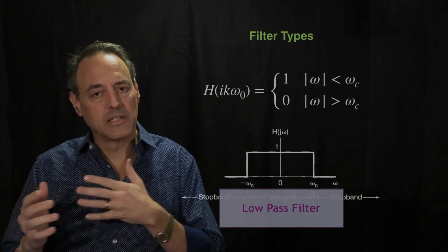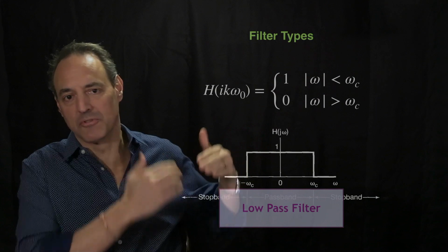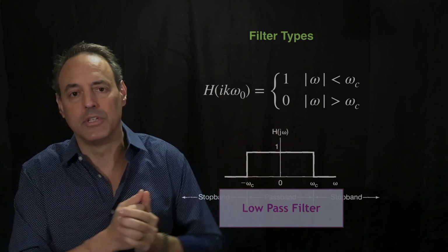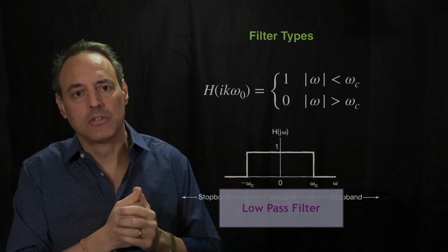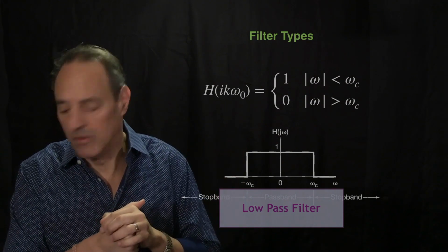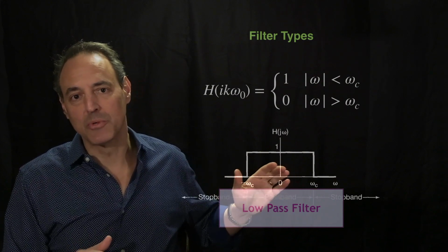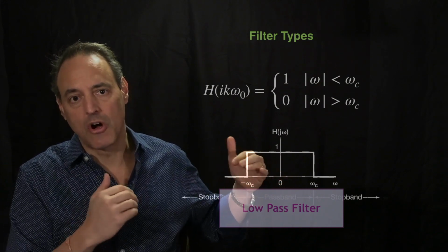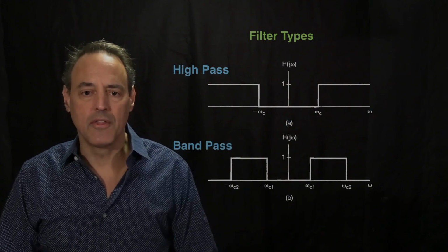Typically, this is an idealization. You can't make filters this clean in terms of exactly killing off frequencies. And there are also implications of sharply cutting off frequencies. Oftentimes what we do is make a low-pass filter which is a little smoother than this very strong notch filter that we would have. You can make other types of filters.